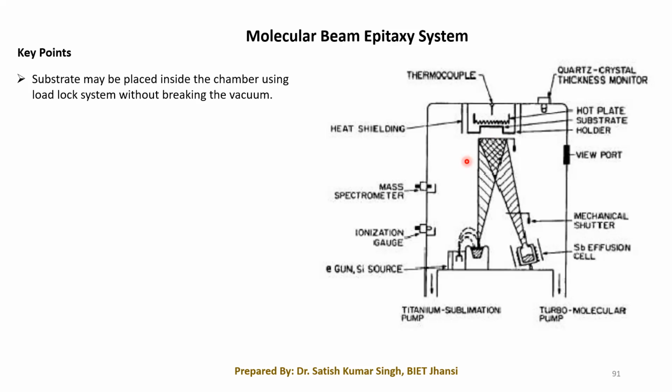Not only that, if other molecules are available within this, then it is also going to deviate these paths. If they get ionized because of the high temperature, they will contaminate. It will not have the proper beam emissions and it is not going to strike onto these surfaces. It may be going somewhere else. So we need to evacuate it properly. Proper evacuation is needed.